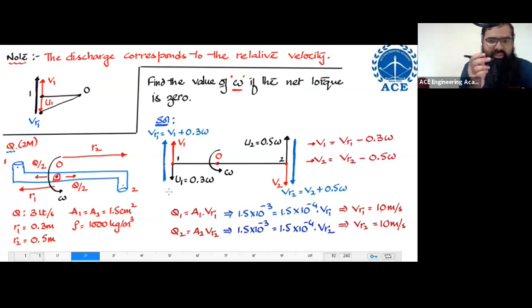To imagine this rotational torque at the hinge, try to imagine opening a door which already has some rust at the hinges. You will find that there is some resisting moment. It will create some kind of sound also. That resisting moment is a frictional torque or resisting torque at this particular point. That value is set to be 0 here. That means the rotation right now is free rotation. Just by virtue of the fluid coming out, this nozzle is rotating. It is not having any torque over there.